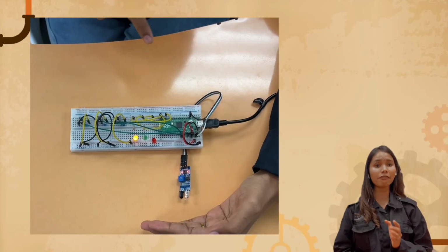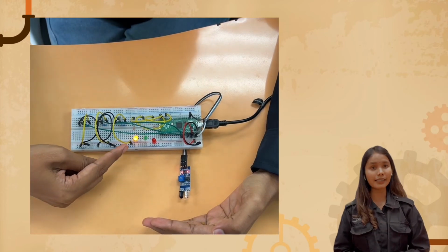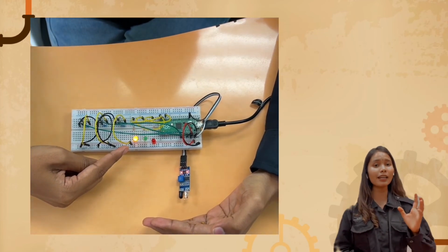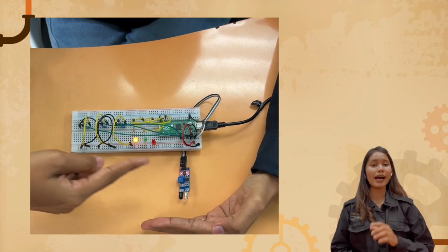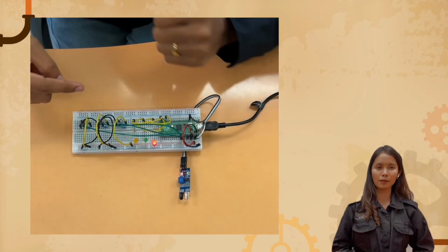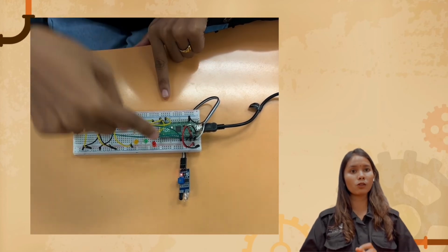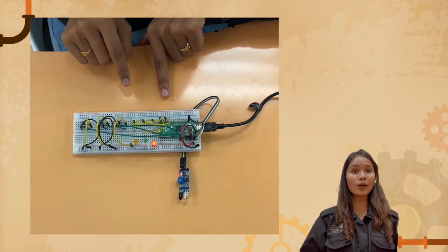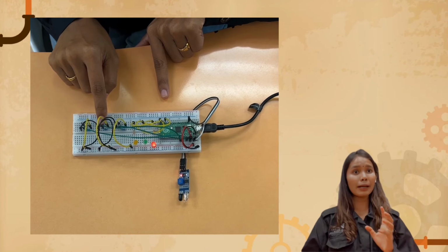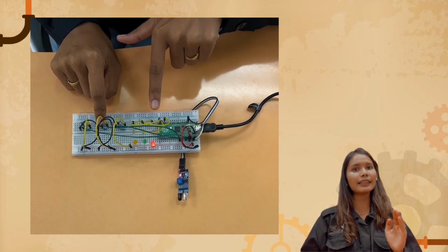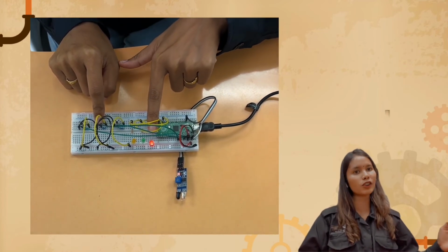During the closing operation, if any obstacles are detected in the path of the gate, the gate is automatically stopped and the orange LED lights up. When the obstacle is removed, the gate continues to close. Hence, the orange LED will be replaced by the blinking red LED until the gate reaches limit switch 3.